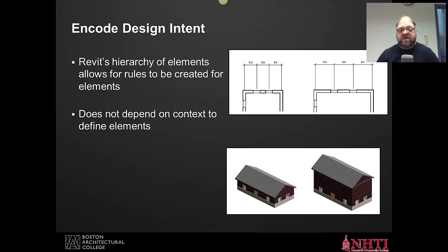Another example of design intent that is maybe more intentional, but you can build these rules around and within your project. So here I'm showing this equality constraint. Some windows were placed into this wall, and I wanted to make sure that they were equally spaced from the edges and between each other.